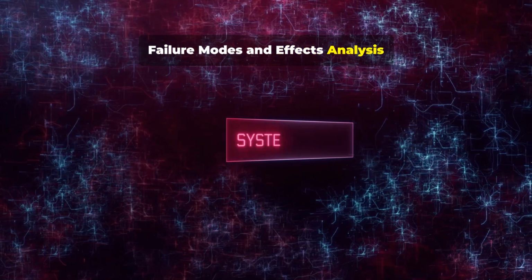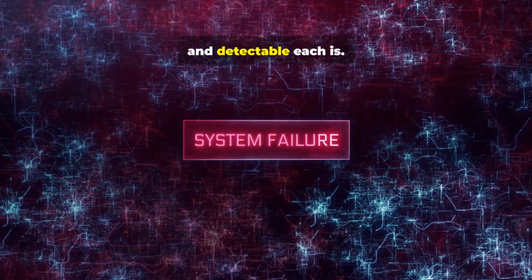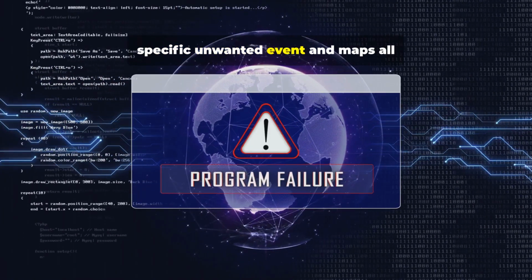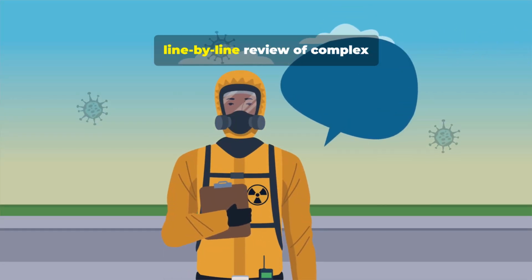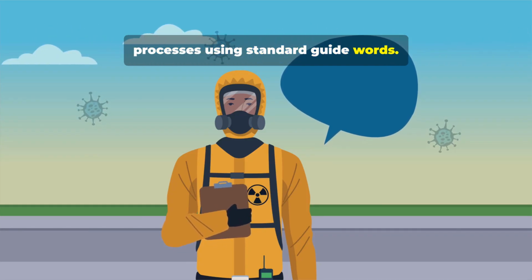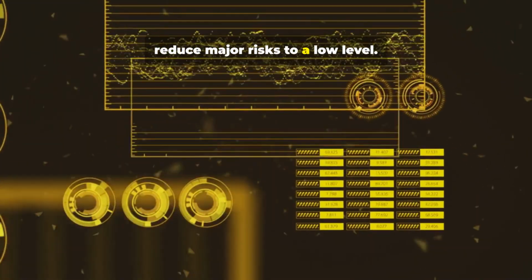Failure modes and effects analysis examines how each part or step could fail, the effects, and how severe, likely, and detectable each is. Fault tree analysis starts with a specific unwanted event and maps all combinations of failures that could cause it. A hazard and operability study is a rigorous line-by-line review of complex processes using standard guide words. Layers of protection analysis checks whether independent safety layers, in combination, reduce major risks to a low level.